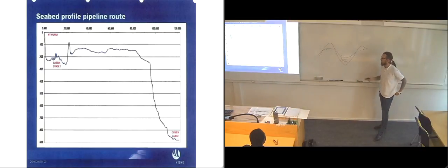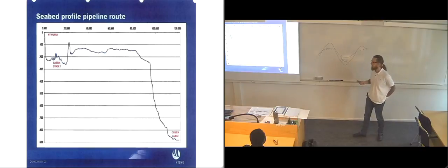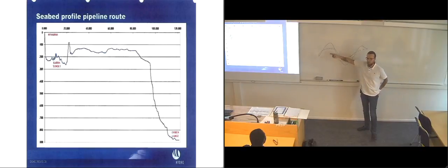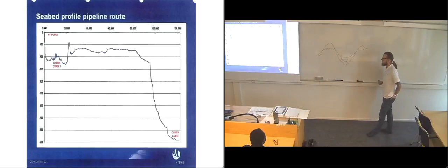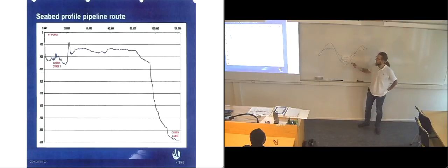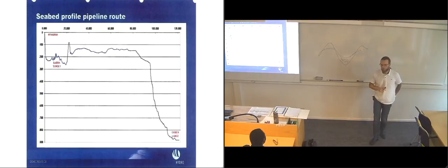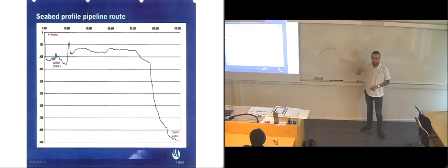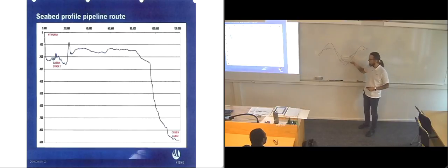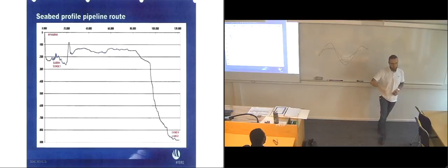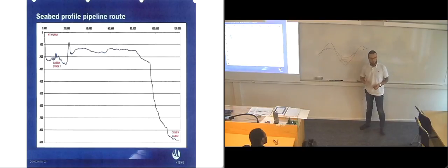That's some of the things that they do when they run surveys along pipelines, when they have ROVs basically just following the pipeline and filming it with their cameras. One of the things they're checking for is that the ocean currents haven't washed away all of the support material beneath the pipelines, because it can actually do that. And in areas where too much has been washed away, they actually have to come back in and refill so that they get enough support for the pipeline.